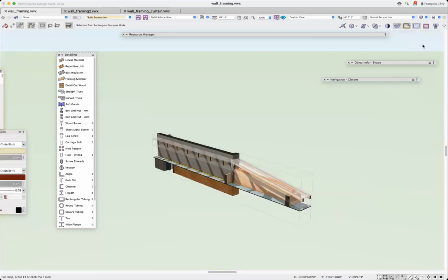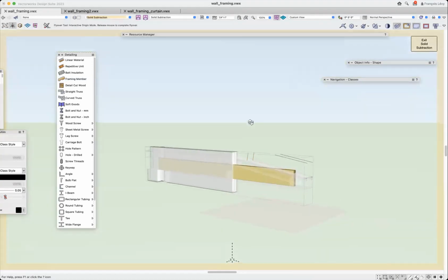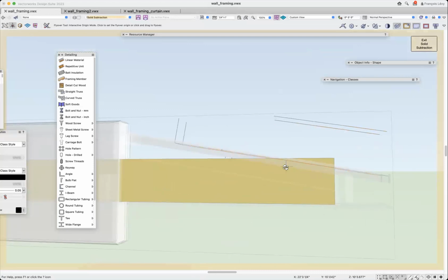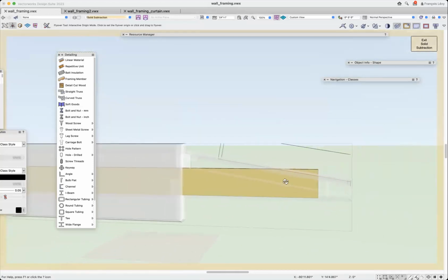In this case, I had a little extrusion here that I'm highlighting that matches the pitch of the roof, so that I could clip off the very top of that beam so that it doesn't stick out above the roof plane, right? You can see that there, even though everything's ghosted in. So it's registered to the underside of the plywood decking.